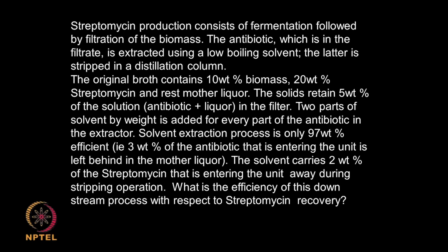Now, whenever you remove biomass in a filter, there will be some liquid in the biomass, because the biomass will not be 100% dry. So, when some liquid goes, product streptomycin will also go with that. So, you will lose some streptomycin. Now, when we go to an extractor, we are adding a solvent.